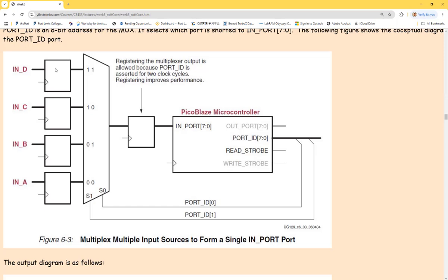They are inside. Okay, so if this core has a CPU, has an ALU, has the ports, has the peripherals, a data path, all the control units, and all these are getting synthesized, and eventually the Verilog is converted to a huge digital block, and that digital block has these 8-bit ports, 256 of them, inside the block, okay? And these are not physically shorted to the pins. But why are these still useful? That's because you can have multiple microcontrollers on the same FPGA, right? Yeah, that could be one of the applications.